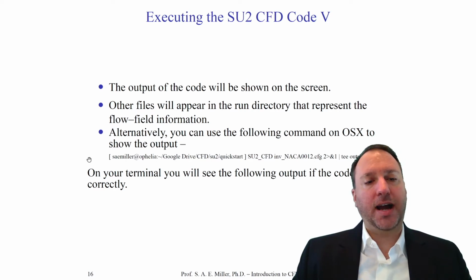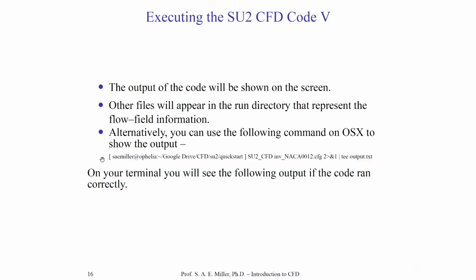Now, a command I prefer to use is shown right here. I put that as my username, my computer, and the directory I'm running, quick start, and I've typed in on OS X, this won't work on Windows, SU2_CFD space my configuration file name, inv_NACA0012.cfg. Remember, I can name my configuration file anything I want.